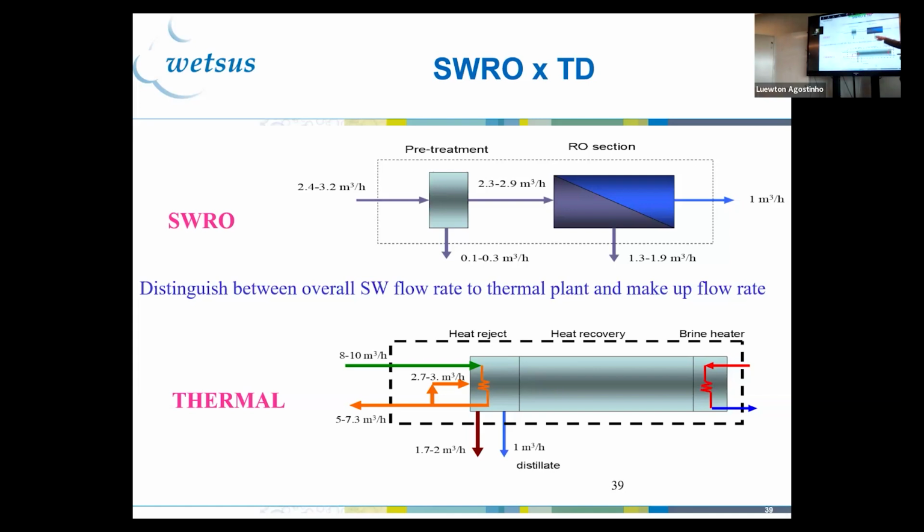This is fresh water. The light blue is fresh water, and the dark blue is concentrate, okay? So you're putting 3 liters in, you get 1 liter of permeate and 2 liters of concentrate. What is your recovery rate here? 33%, 30%, which matches that table, right?